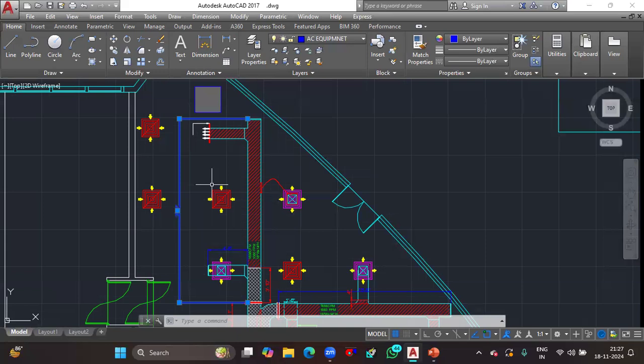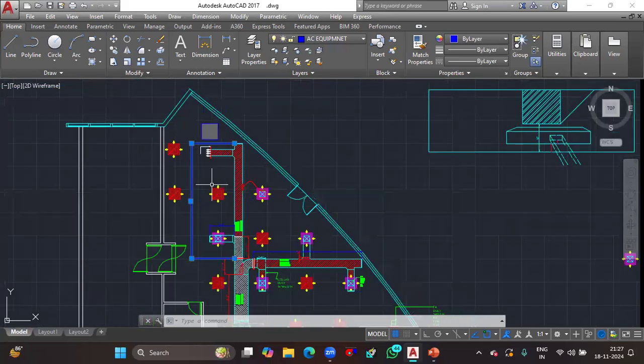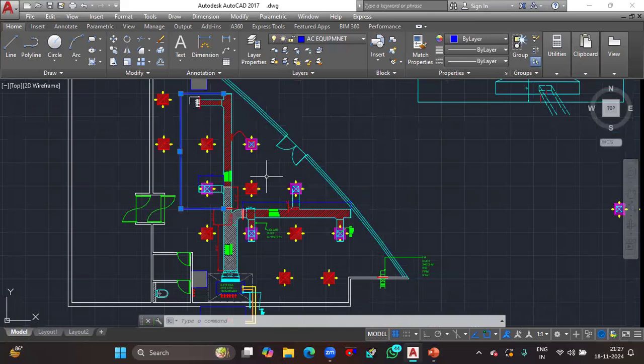It is due to friction. The same scenario happens inside the ductwork also. As the air flows across the ductwork, it will eventually lose its speed and flow rate. So in order to assure that, we need more boosted fans for these projects, especially for custom-built air handling units and complicated ductworks. At this time, we need to replace the fan motor with an apt one.